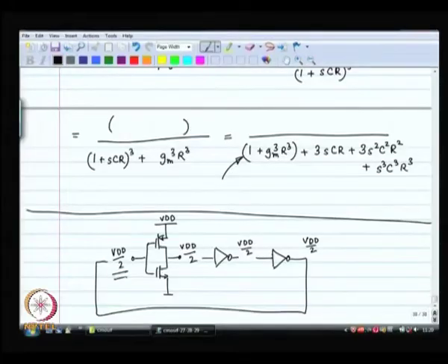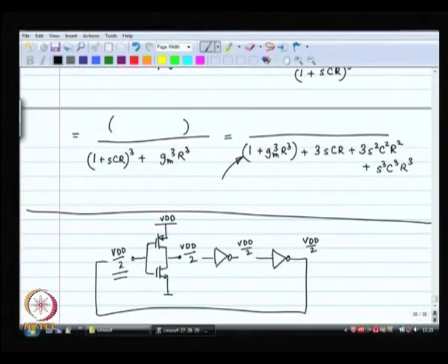So, this VDD by 2 is no longer going to remain, because something has changed, perfectly balanced, something starts moving away because of the poles being on the right half plane, and as a result it is no longer going to be at perfect balance everywhere. So, this is basically the idea. This is why we did the pole 0 analysis, to prove that this thing is indeed going to oscillate. Did not really complete it, because I can't find out the poles of a cubic, the roots of a cubic by hand, but I gave you the way.